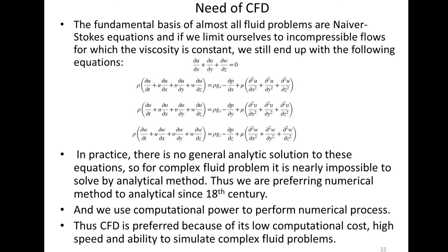These equations are very good at approximating or modeling the physical behavior of fluids into a mathematical model. Just ignoring the turbulence, all sorts of fluid problems can be modeled in terms of the Navier-Stokes equations, though they don't have any features or any idea about turbulence, but they include the viscosity.